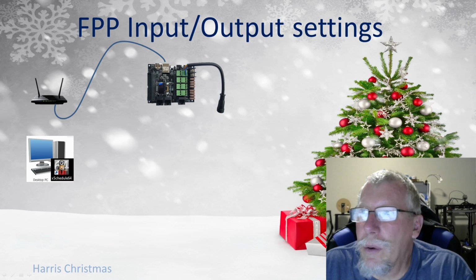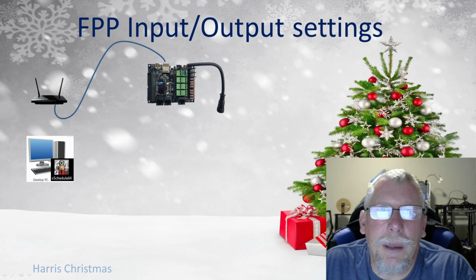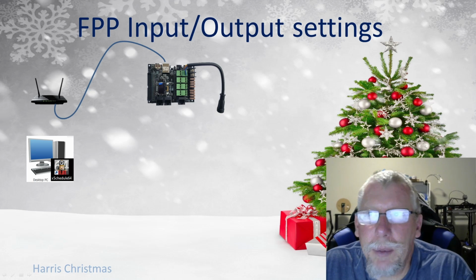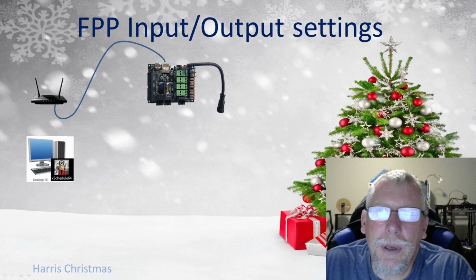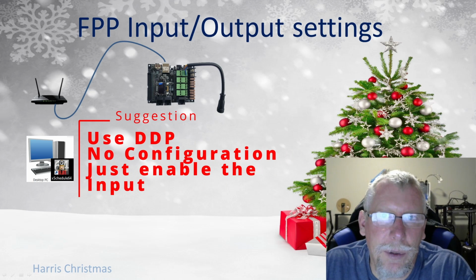All right, let's go over the FPP input and output settings. A common mistake that people make is in understanding and configuring the inputs and outputs of an FPP device, and then they have problems with lagging or poor quality playback. Hopefully this section will clear that up a little bit. The good thing is that if you properly configure your controllers in xLights, when you upload the configuration to your FPP devices, your outputs will be configured properly. Unfortunately, right now the inputs don't get configured and you have to do that manually.